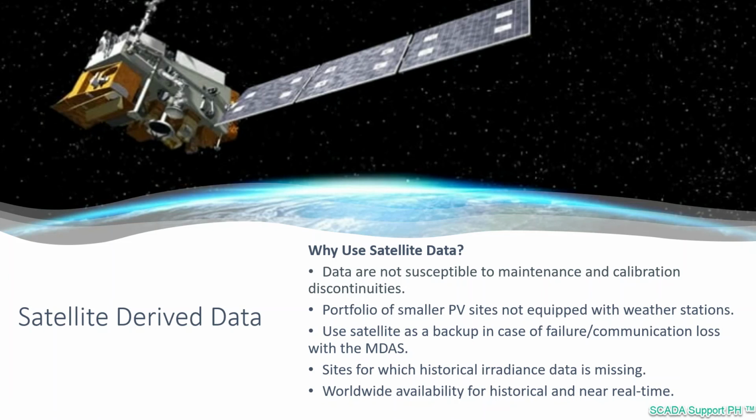For locations that have a low density of meteorological stations and rely on satellite data, site solar resource monitoring may be considered during the feasibility stage of the project. In general, the measurement data for a minimum of 9 months can be used to reduce existing bias and improve the estimation of the long-term mean.